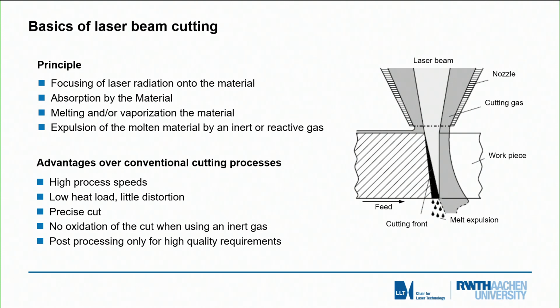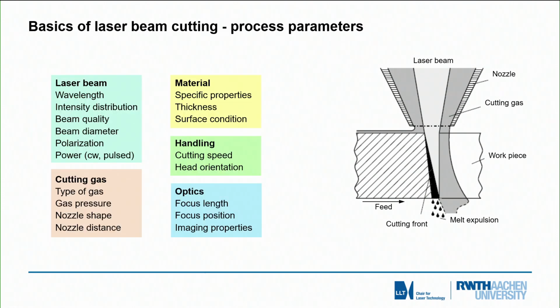The advantages of these cutting processes compared with conventional processes are that we can have much higher processing speed, low heat load, little distortion, very precise cuts, and no oxidation of the cut if we use inert gases. And in most of the cases, post-processing is not required.